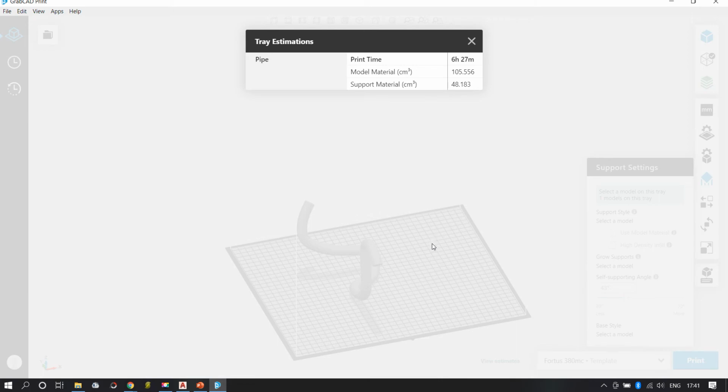Then you will be getting rid of the support material on the front side of the face, instead of turning it upside down. That is also a different issue. That means where you want the support materials and all those things. There are some very good softwares where you can even design the support materials. I hope you will be able to see the software when you will be demonstrated these things in details, but this is the basic of how the orientation can be decided.